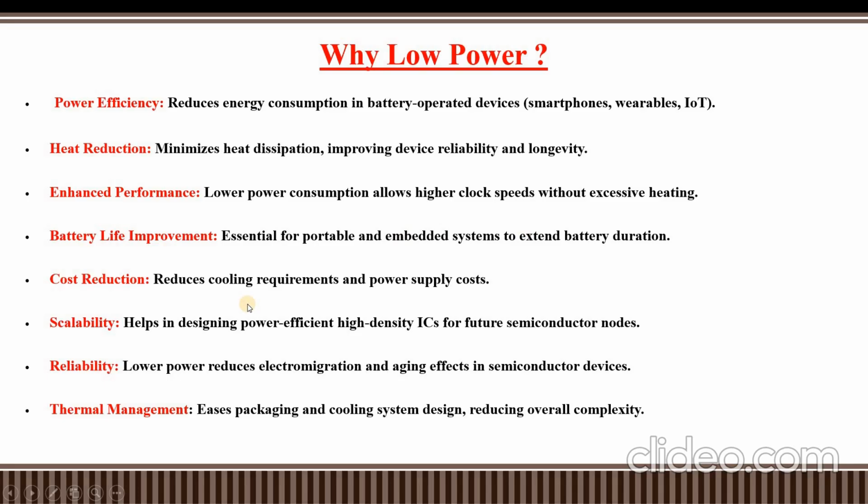The next reason is cost reduction. It reduces cooling requirements and power supply cost. The next one is scalability. It helps in designing power efficient high density ICs for future semiconductor nodes. ICs means integrated circuits. The next one is reliability. Low power reduces electron migration effects and aging effects, and it can improve the reliability of the device. The next one is thermal management. It eases packaging and cooling system design, reducing overall complexity, and we can also say it reduces packaging and cooling cost. For all these reasons we require low power.